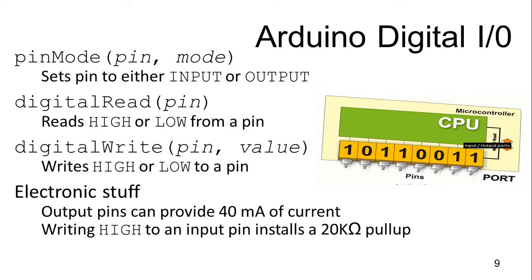Okay, let's talk about the Arduino pins, the digital input output. We use this command called pinMode, and the protocol is that we write the pin number and the mode. Mode will be either input or output. Pin will be the pin number.